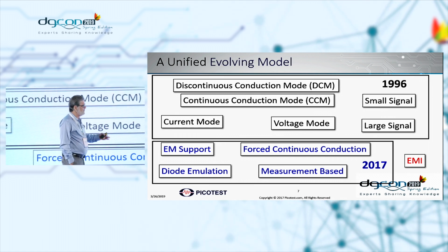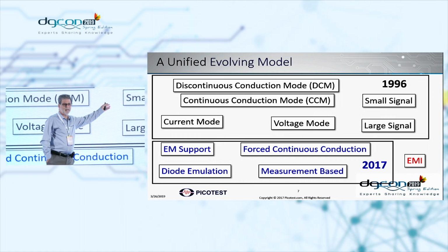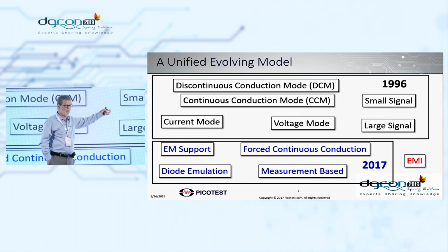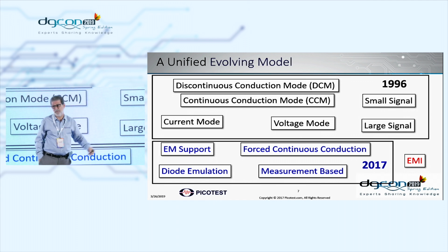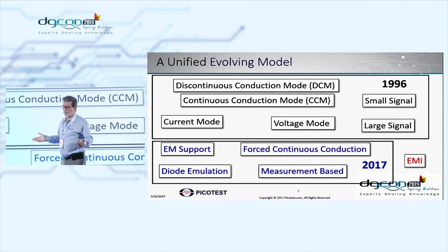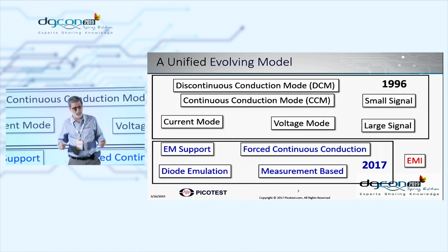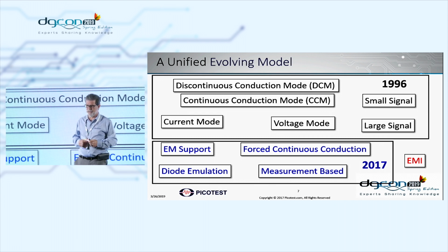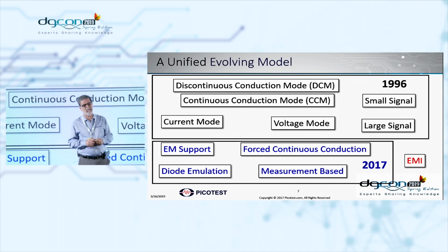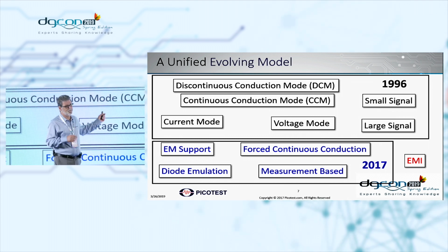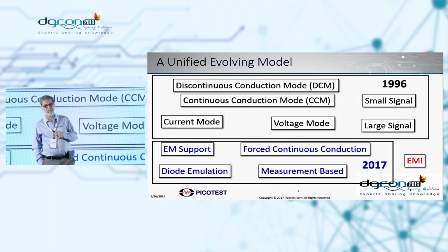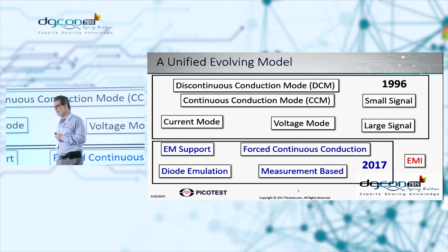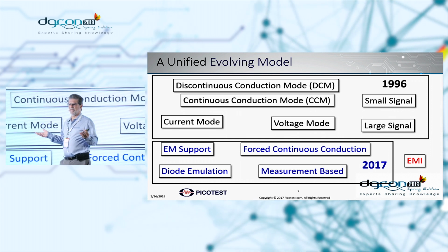And maybe even more importantly, I needed something that could do not only small signal analysis, which most state-space models are designed for, I also needed something that could do large signal. The differences are really profound. In small signal, we're looking at small perturbations, and we look at the responses to the perturbations. But in the real world, not everything is small signal. In fact, the first use of my model was to perform a simulation of the International Space Station as it goes through eclipse. And when it does that, some really interesting things happen.